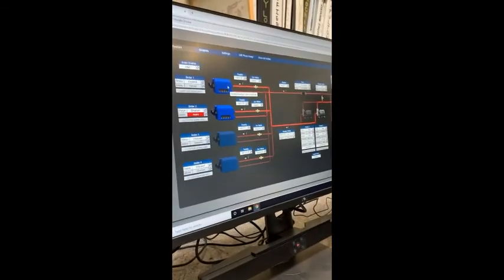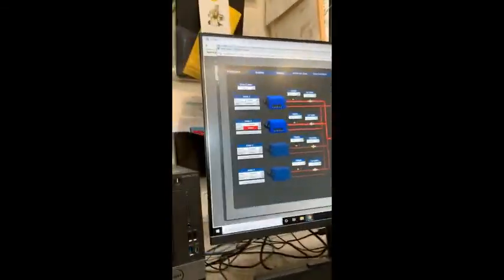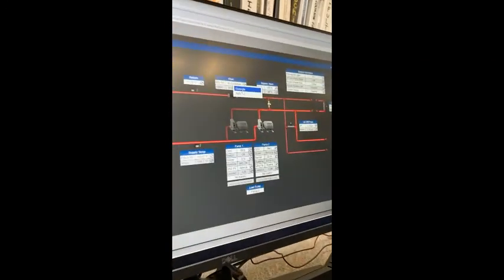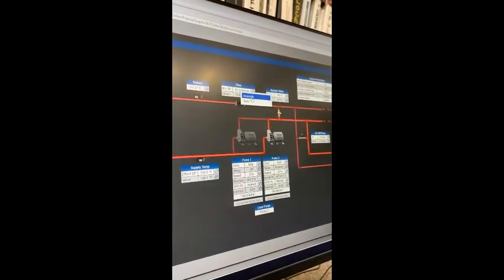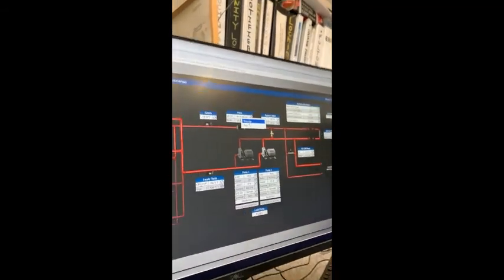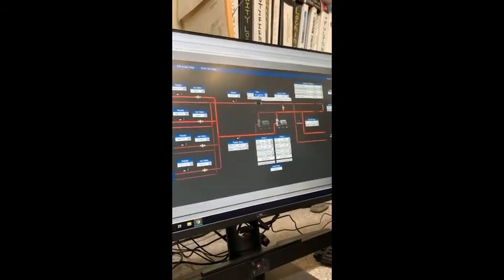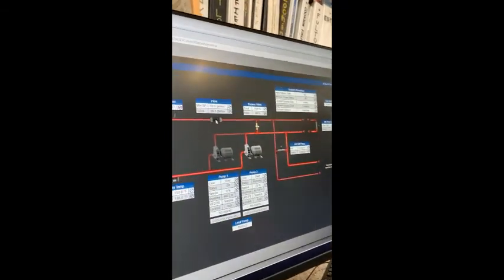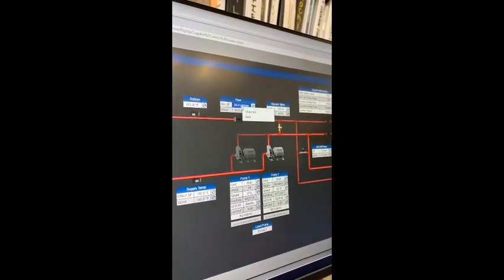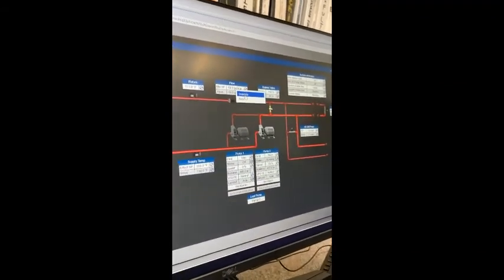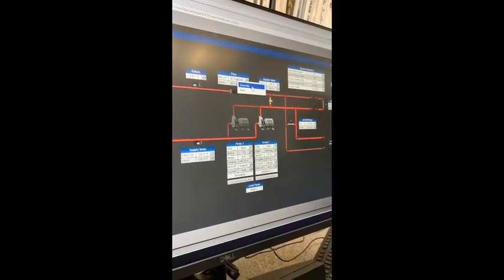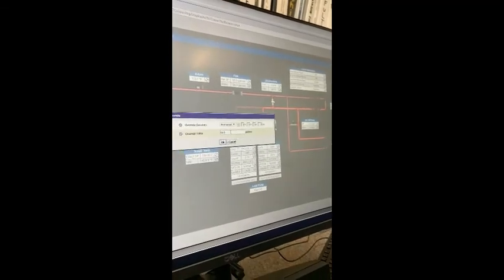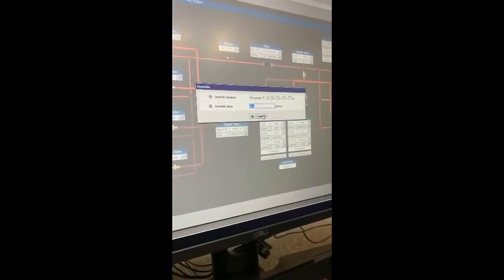So that's the difference between those two types of actions, the override and the set. So there's no preset on those set ones? No, when you change them, they're changed, and that's it. Now the override we looked at earlier was a true or false, an on or off command type. This one here is a value, what they call a numeric value, a number that can change. So there's no on or off for that, and you only get two override options here: you override the actual value versus overriding it to a state of on or off.